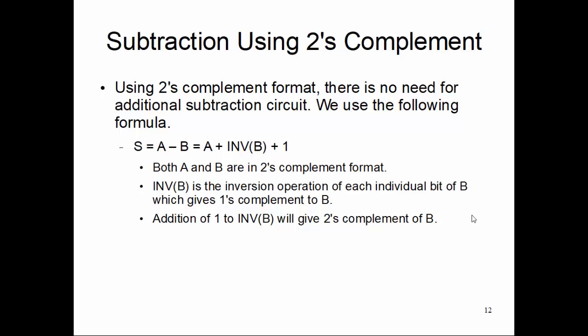Now minus b, like I have an amount. Let's say, for example, I have an amount 15. Okay, 15 in an 8-bit 2's complement example. I have an amount b equals 15, and I have another amount a equals 5. Okay, so I want to do a minus b in 2's complement format. So 5 minus 15 results in minus 10, right? Now that I can say as 5 plus minus b, minus 15.